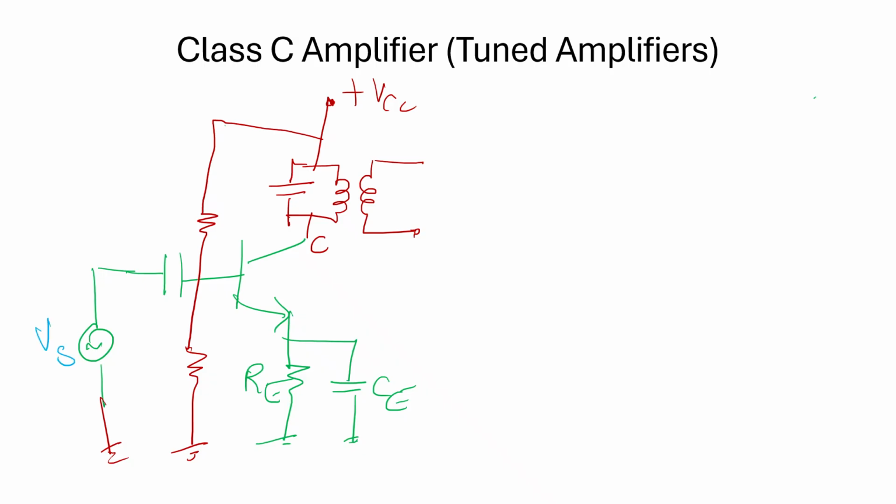So this is the source voltage Vin, and the coupling capacitor. This part of the circuit is a resonance circuit. R1 and R2 are the voltage divider circuit. The base and the emitter. Here, when the input signal is given, the amplifier amplifies through the resonance circuit and the amplitude of the output signal is obtained here.